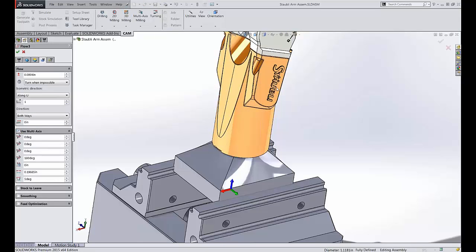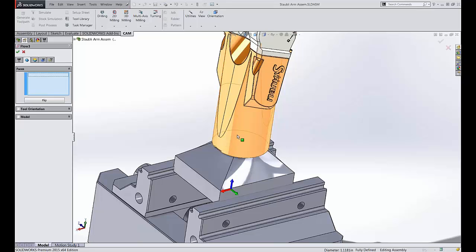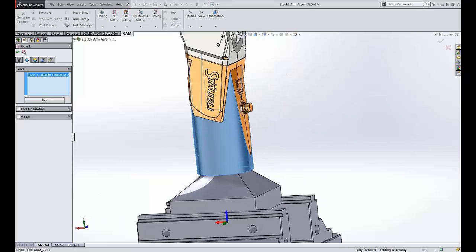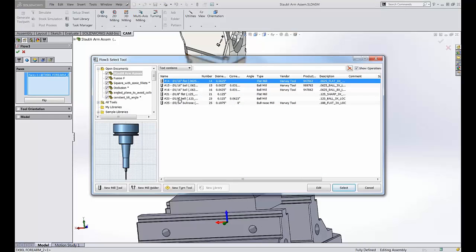Again, actually I think this should be a good example of it, hopefully avoiding collision or avoiding running into adjacent surfaces. Okay. So we'll go to about 35 degrees. We'll tell it to produce about 100 passes. We'll select this guy. Oh, and we need a tool, of course.